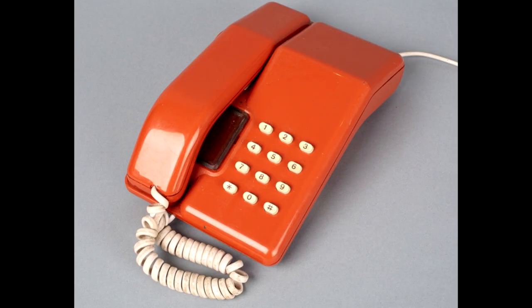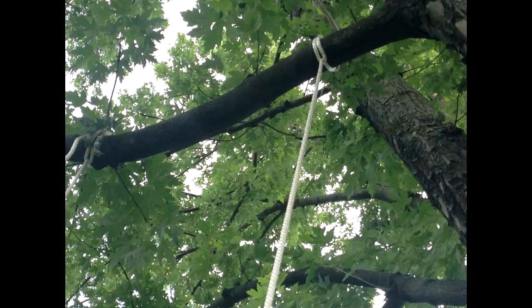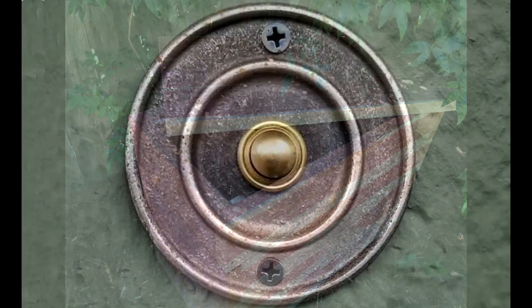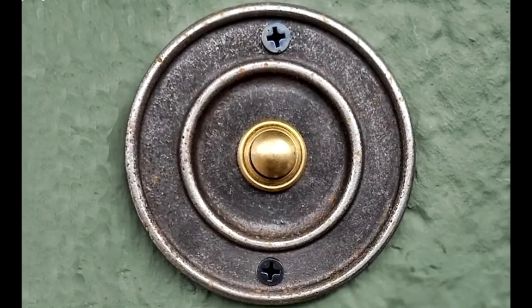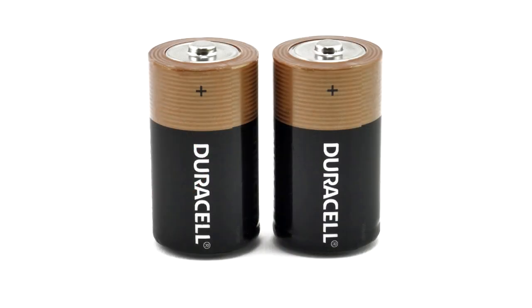Actually, you do not need a phone at all to make an audio cache. For example, your cache can play a message when a hidden door is opened, an object is lifted, a string is pulled, or whatever. Even just a disguised button pressed by the cacher. For any design that only requires the audio module, you wouldn't even need a large rechargeable battery. Just install a battery holder for 2 size C or D batteries connected to the 3.7 volt power input instead of the 5 volt. Change the batteries periodically as needed. Even if the cache is highly active, large disposable batteries will probably last well over a year before needing replacement.